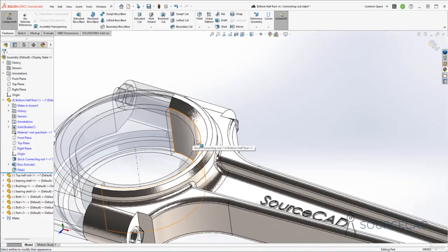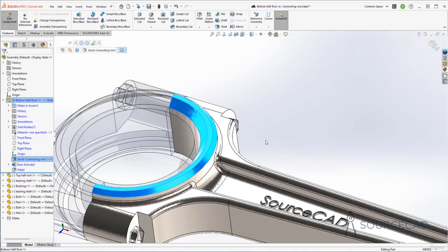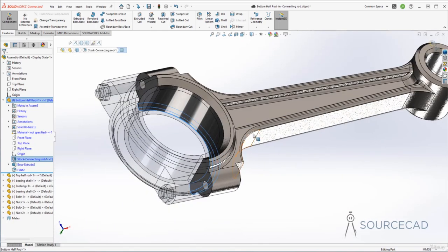Now, instead of selecting it one by one, I'll simply select all the faces using Control key. So I'll select this face, and this face. So these are only the machined faces which I'm selecting here, and then I'll orbit it to this side. Then select this face, and this face. And remember, I've got my Control key still pressed, and then we also have, well, this face and this face. Though we can ignore these faces because, well, these are the machine faces which will be machined later, but this can be sandblasted as well. So I'll just leave it.